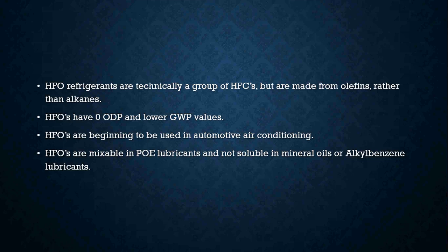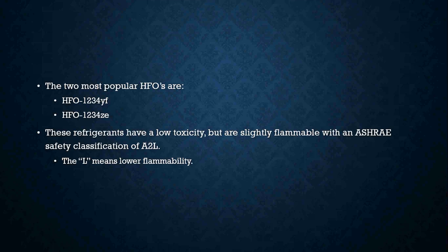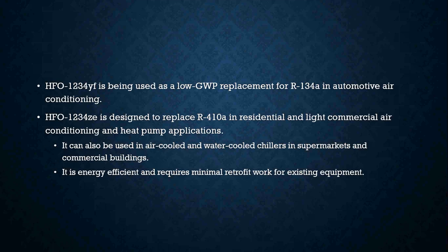You will see HFO refrigerants being used in automotive air conditioning. When used in automotive air conditioning, they are miscible with POE lubricant and are not soluble in mineral oils or alkylbenzene type lubricants. Common types of HFOs out there now are your 1234YF and your 1234ZE. These refrigerants have low toxicity but are slightly flammable, with an ASHRAE safety classification of A2L. The L stands for lower flammability.